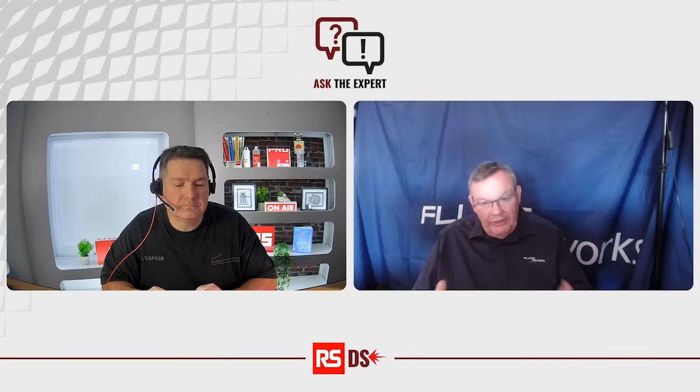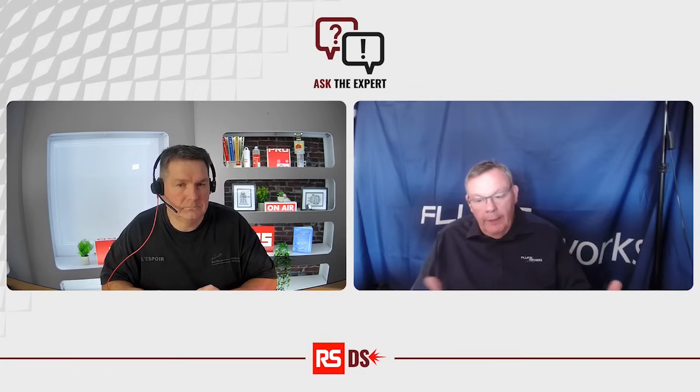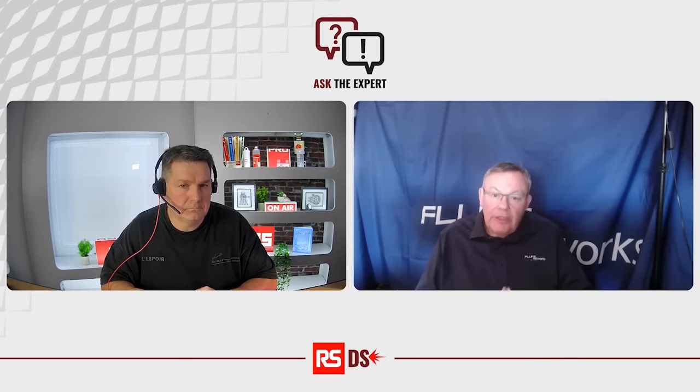When we're looking for significant amounts of available bandwidth, so when we want to transmit large quantities of data, either between network and human or network to network, we're concerned with the quality of the cable installation. The available bandwidth is dependent on how the cable, to a certain extent, how the cable itself is treated, and then more importantly, how it's terminated. So how the cable is handled literally in the last, let's say, foot or meter, while the cable is being laid into tray or put into a building, how it is maneuvered, and then how that last, let's say, 6 inches of the cable is handled when we're putting the connector on the end can be crucial to the way it performs.